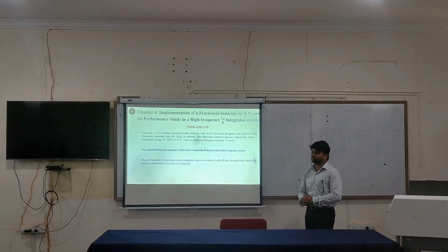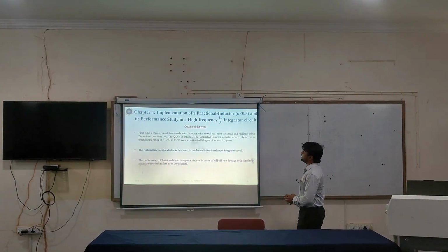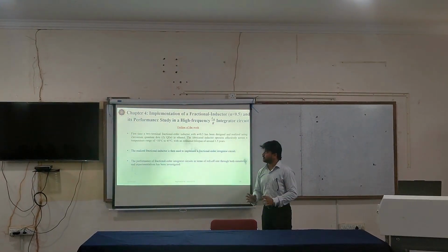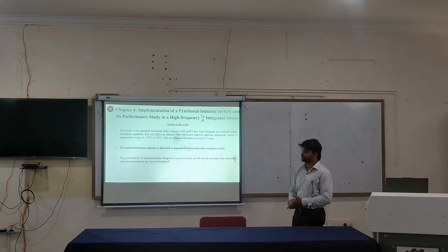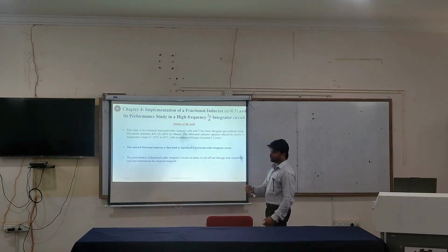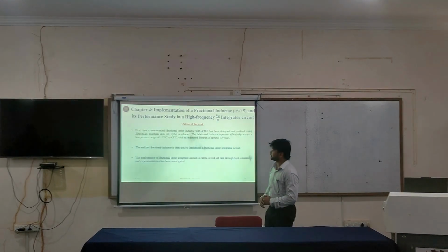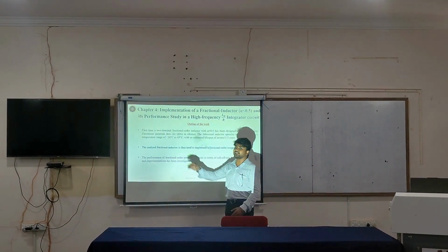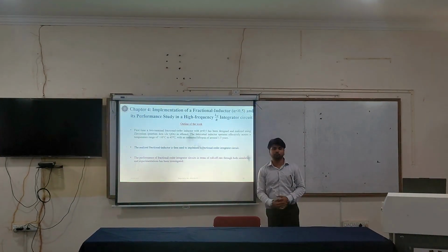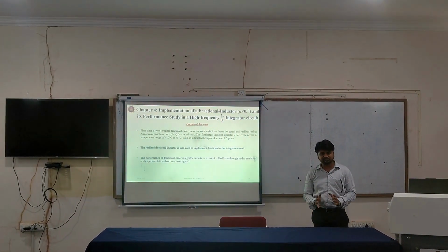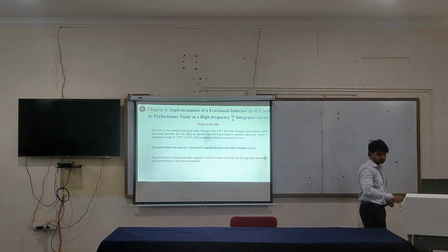Implementation of a fractional inductor of order less than 0.5 and its performance study in a high frequency integrator circuit. For the first time, a two-terminal fractional order inductor of order less than 0.5 has been designed and realized using zirconium quantum dots diluted in ethanol. The fabricated inductor operates between a temperature range of -10 degrees to +45 degrees Celsius and has a lifespan of more than 1.5 years. This has been realized and also used to design an integrator circuit.